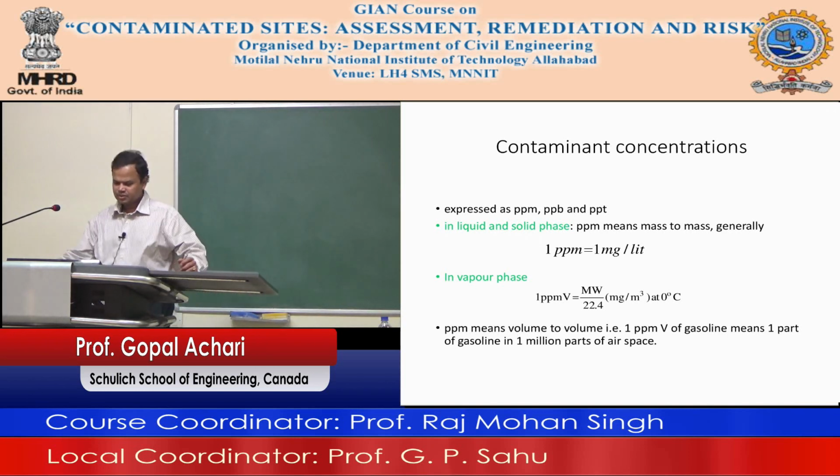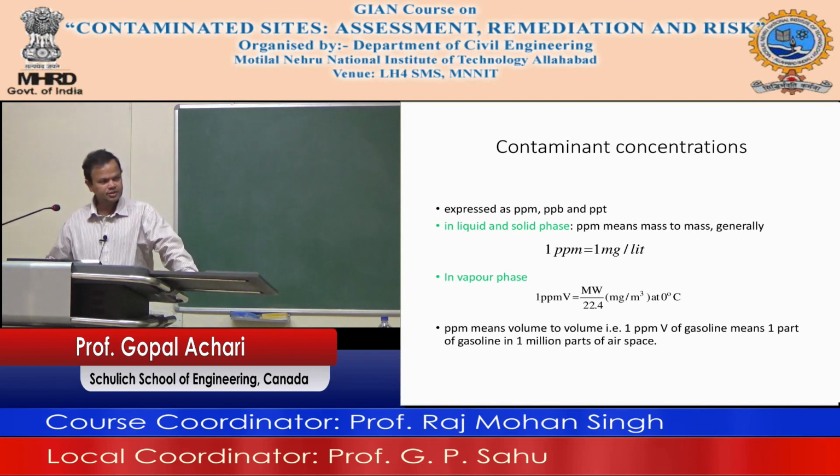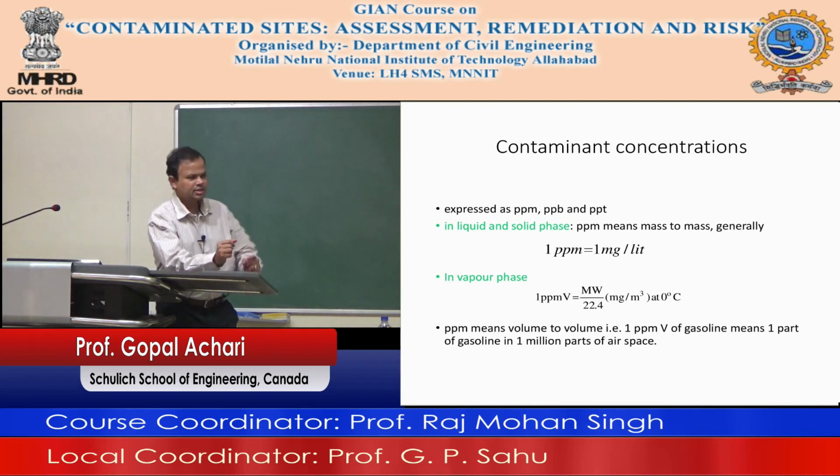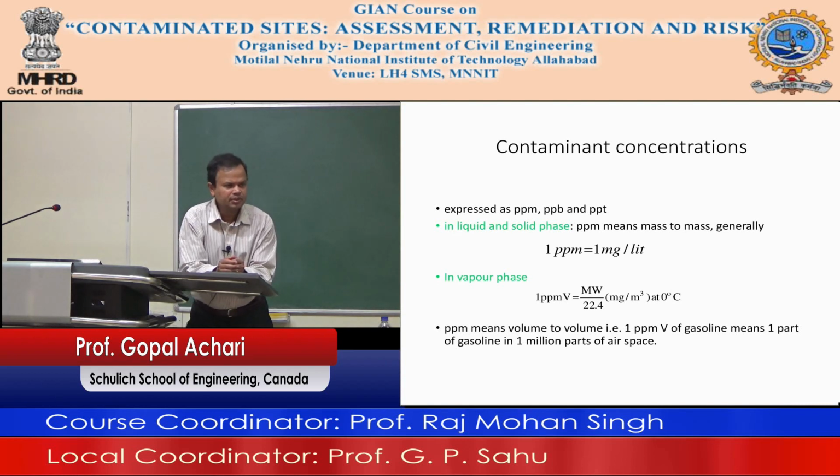You have to think about the effectiveness of the system that you're planning, cost, time, level of cleanup. And this is important. Yesterday, I mentioned partitioning of contaminants. If you are doing something in one of the phases, there's a good chance the contaminant will start to move as that phase depletes of the particular contaminant. Are you with me on that?